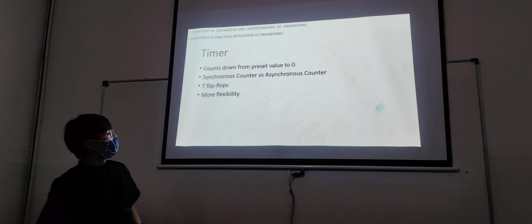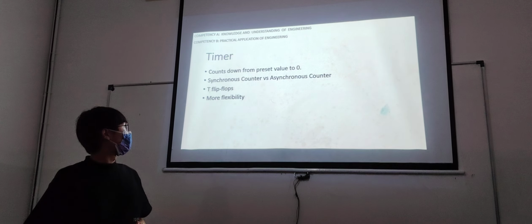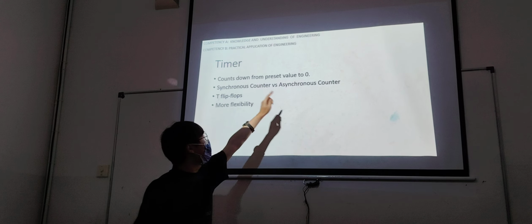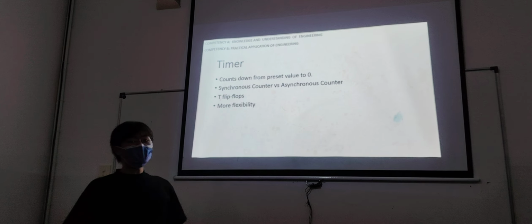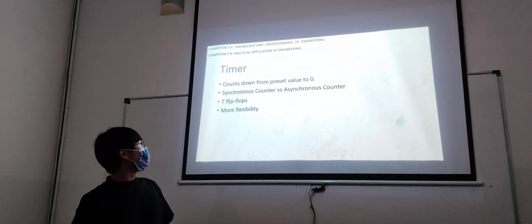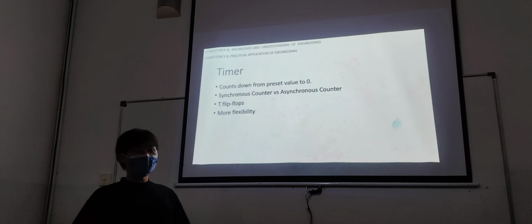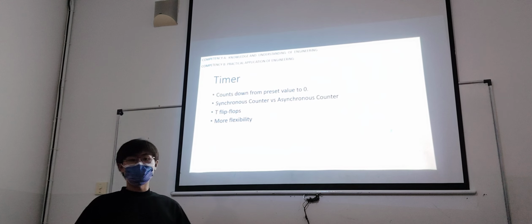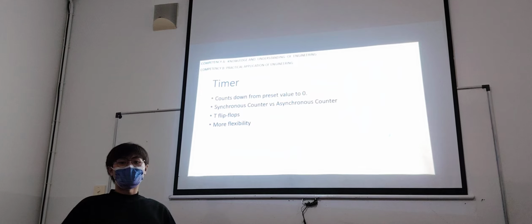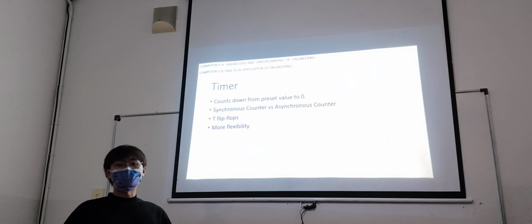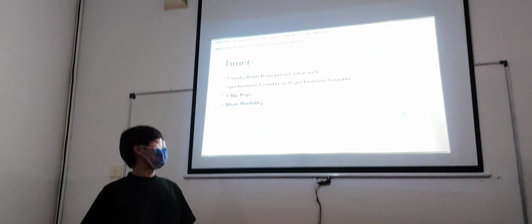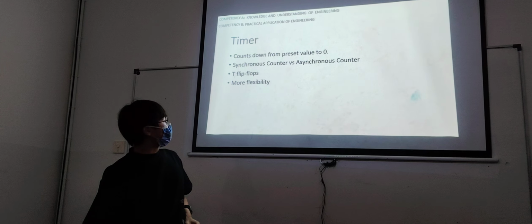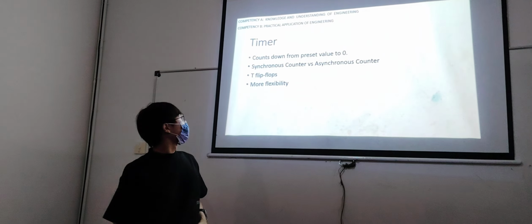Now, the timer should count down from the preset right up to 0. Here we considered using either a synchronous counter or an asynchronous counter. Ultimately, we decided to use a synchronous counter because it provides more flexibility for the design and also for the end user, where you can put any sequence of numbers, whereas for the asynchronous counter, you can only put numbers in sequence. We implemented this using a T flip-flop circuit.